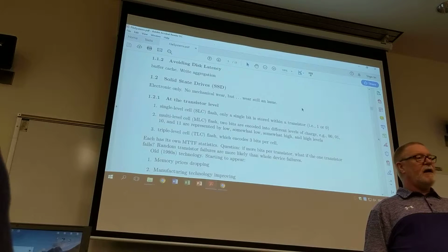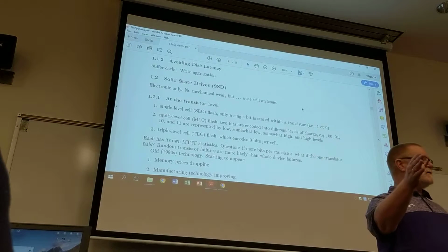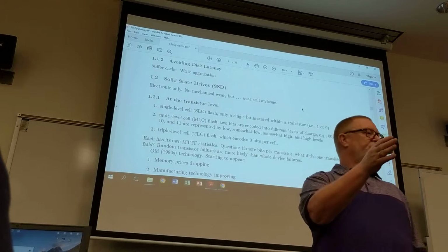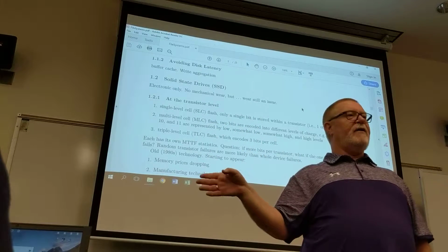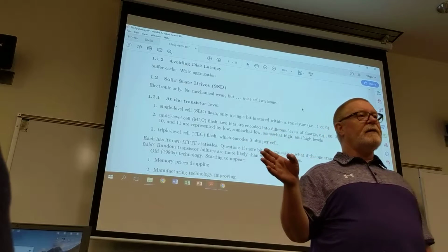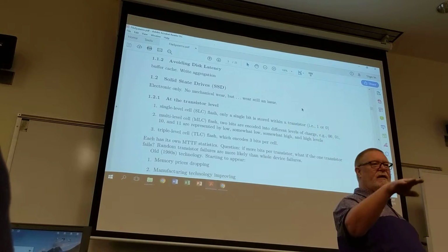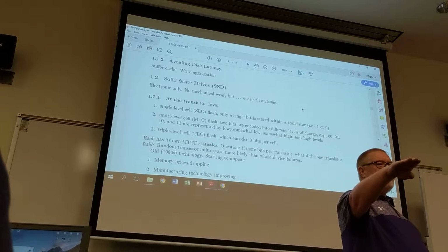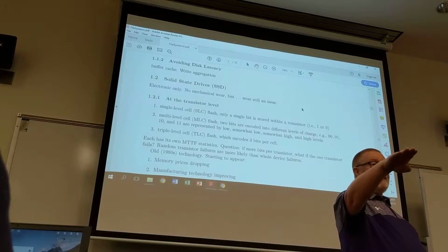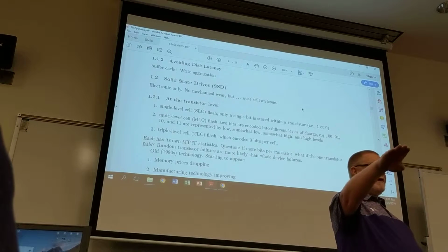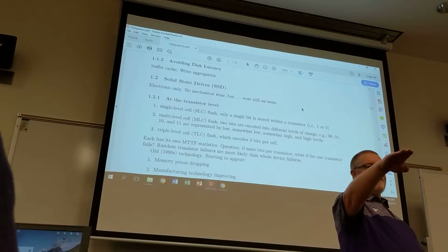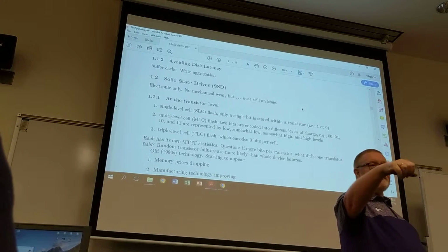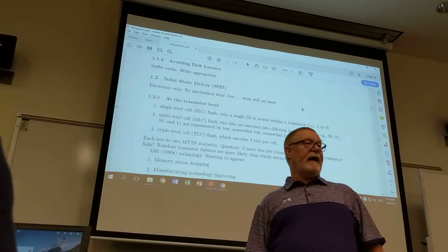And what you might not know is if your disk looks like it doesn't have any work to do, it's not going to sit there trying to hold that disk arm out there at 1/12 millionth of an inch. It's going to take it back to a reserved area of the disk. It's called the landing pad, and it will power down the disk arm and rest the read-write head. Because while it's holding it up there, more wear is occurring on the system because no bearing is perfect. They're not perfectly round. So there's a vibration, but it's trying to hold that at 1/12 millionth of an inch. So they're fighting each other. That's another piece of equipment that's wearing out.